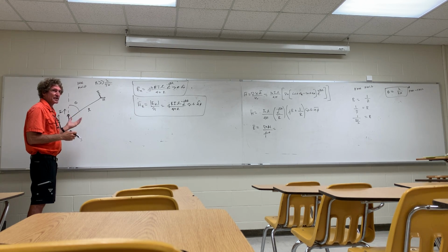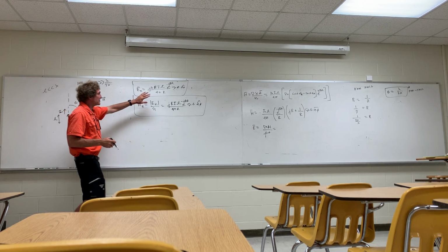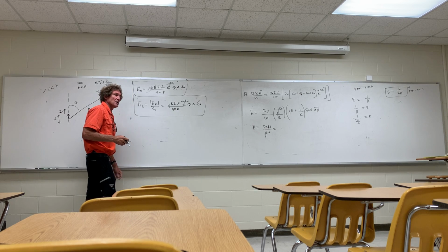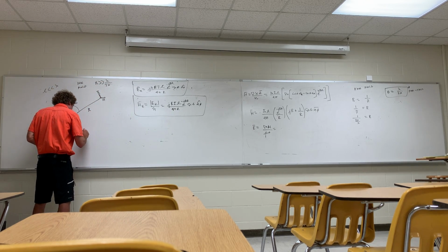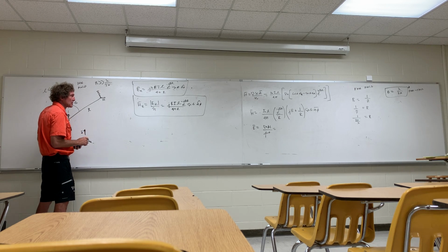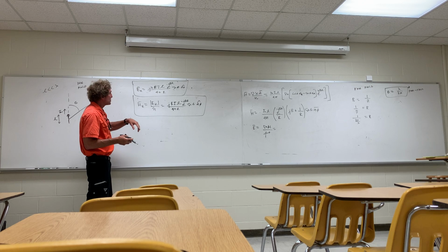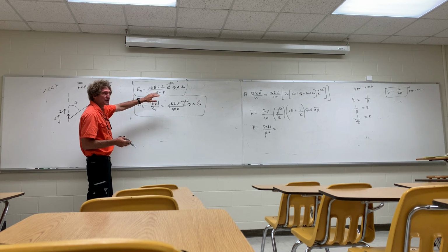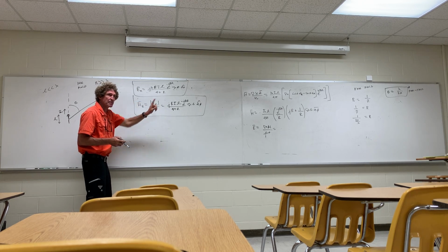Now, there's a couple of things you have to take note of here. Just look at the E field for a second. If I take a look at this short dipole, it's got a current I there. If I was to graph using a polar plot the magnitude of the E field, you see how both of these are proportional to sine theta, right?